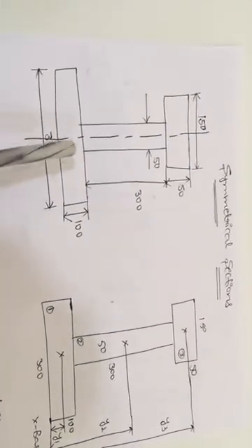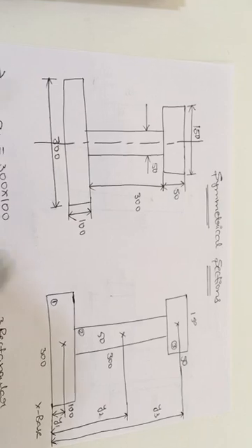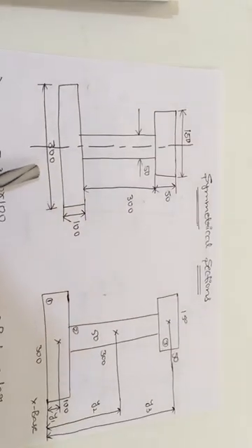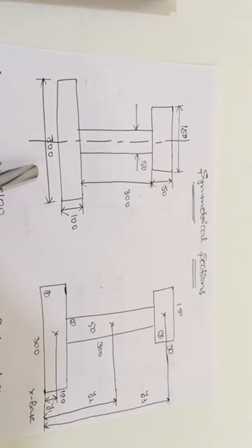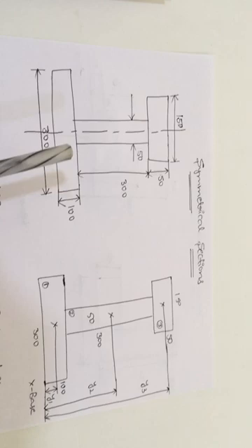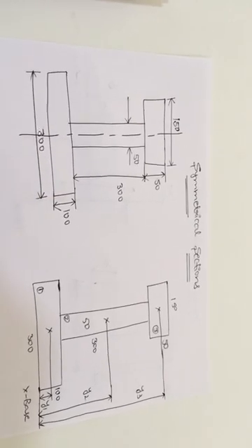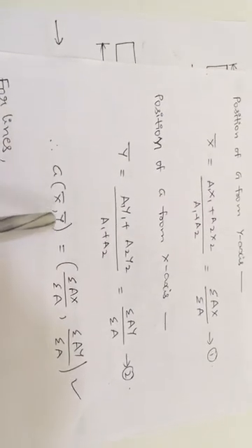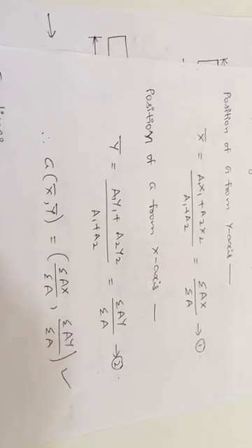So this is our symmetrical section problem. Here three sections are there and this section is completely made of plane figures. So for plane figures you will have only areas. When you have plane figures and you need to calculate the areas, this will be the formula: centroid x bar, y bar is equal to sigma ax by sigma a, comma, sigma ay by sigma a.